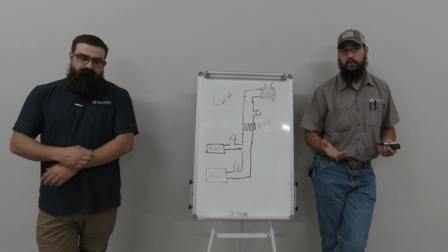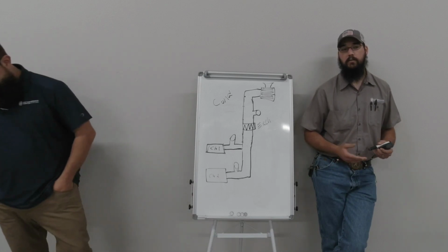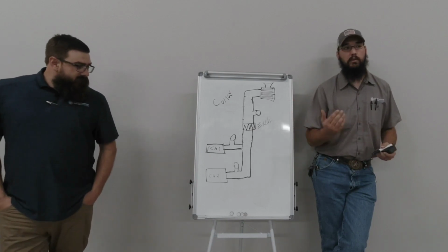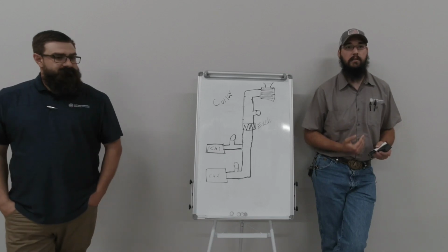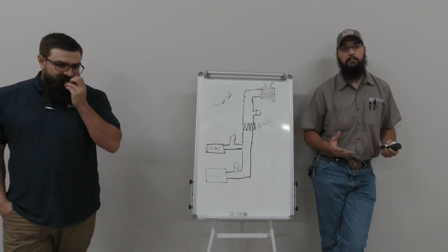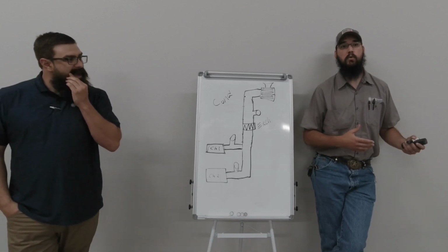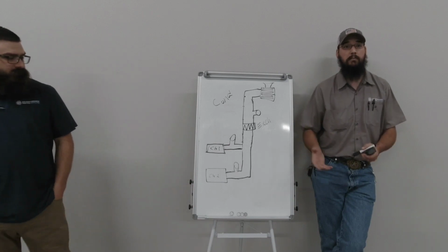And then you start playing into the efficiency and wear and tear game, right? That's a whole other subject. Because you're pushing too much water through there, you're not utilizing that water to its best capability and capacity. And inevitably, your pump is working harder to move more water than it needs to, which is creating extra wear and tear at the pump level.